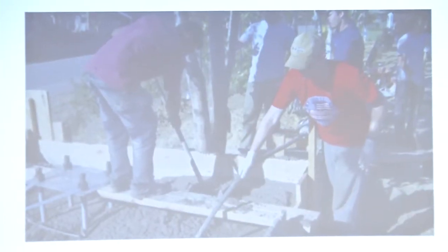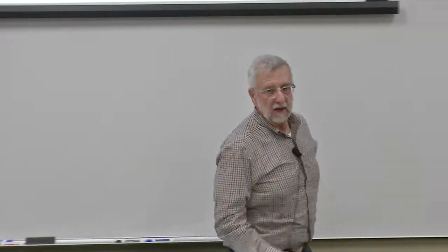Okay, so the process of mixing the concrete is like this. You bring in your sand and gravel mixture, and I forget what the recipe is. There's so many wheelbarrows full to the bags, I don't know. But anyway, you get a sand and aggregate mixture piled up about halfway. You take a bag of cement, drop it on that, break it open, mix it up, bring in some more sand and gravel, put another one on it, break it up, mix it up dry, and then you make a volcano out of it.